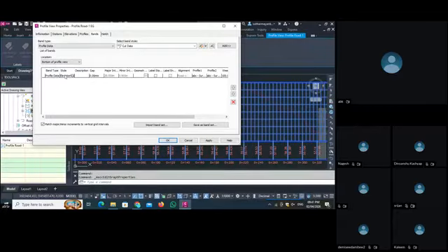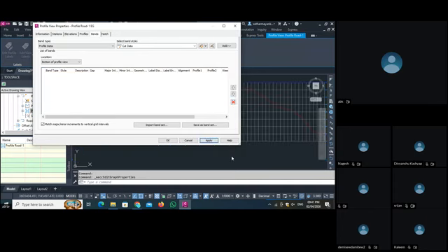So here one bend is automatically created whenever you create the profile, but I don't need this bend. I select this line and click this red button and click apply. So my bend is gone.